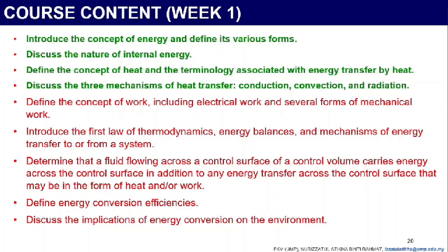We will determine that a fluid flowing across a control surface of a control volume carries energy across the control surface in addition to any energy transfer across the control surface that may be in the form of heat and/or work. We will define the energy conversion efficiencies and the related equations, and we will discuss the implications of energy conversion on the environment.